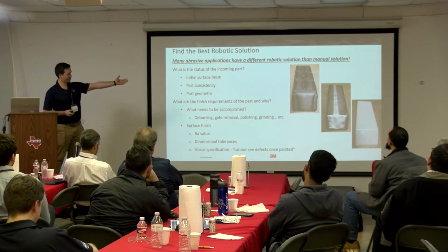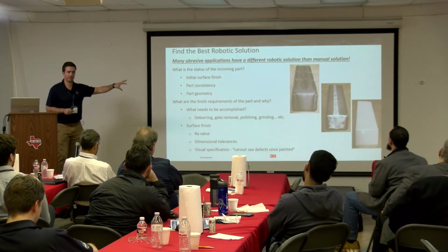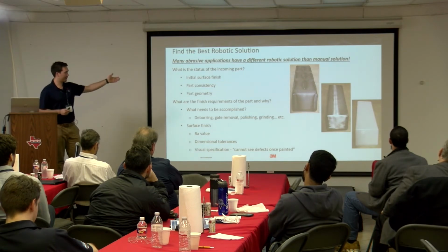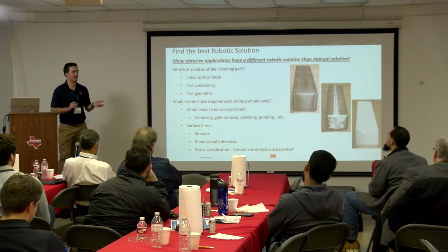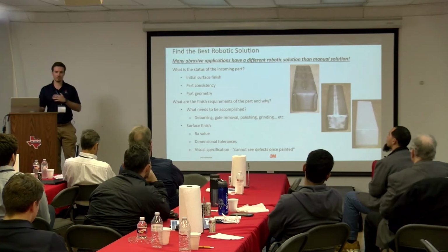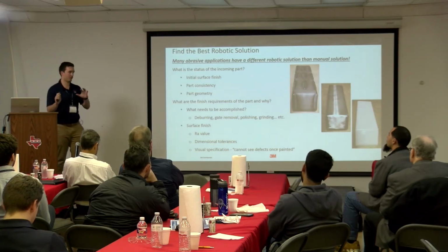If you look at these parts over here, these are some demo ones that we've had. You have some welds on there, you get a finish, and then a powder coat. In a manual operation, a lot of powder coating has random orbital sanding involved. It takes a lot to switch those discs, those pads, but what it does is break up the scratch patterns that an operator adds, so it creates a nice unseen scratch pattern. So when you cover it with powder coat, you can't see it, but with robotics, you can create a nice clean, smooth finish so that it's not necessary to use random orbital sanding in all applications, not all of them.